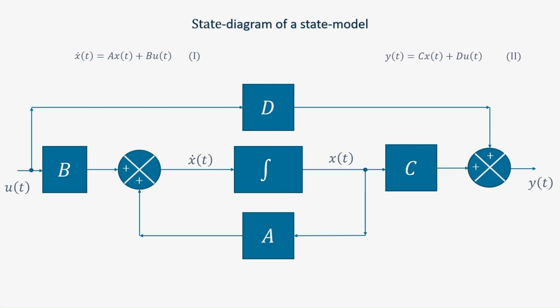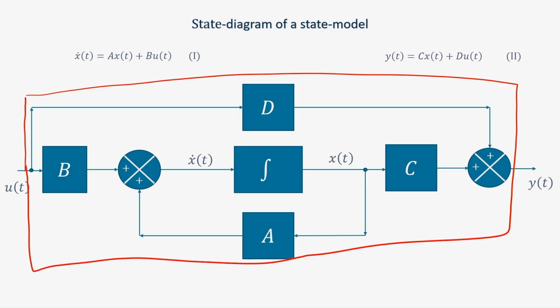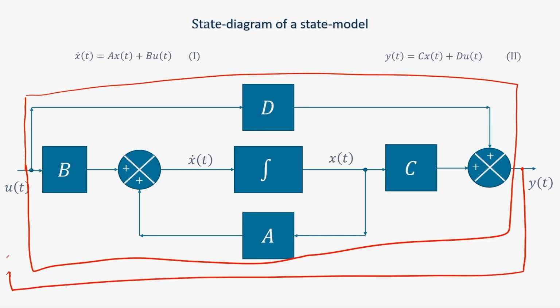So, in the PID case, this was your actual plant. When you were designing PID controllers, you used to tap in here and then feed this signal back into the system. You had an error block or a summer here where you used to give the reference signal, and then this used to go into the system.